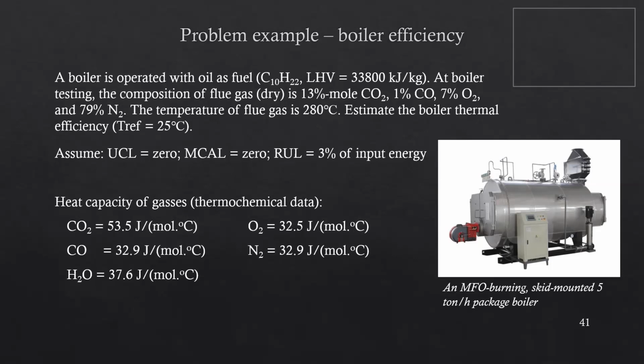And at boiler testing, the composition of the flue gas on a dry basis is 13% CO2, 1% CO, 7% oxygen, and the rest is nitrogen, which is 79%.